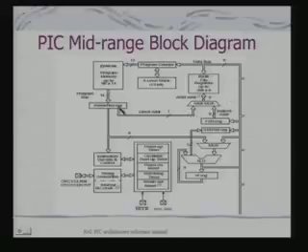This instruction register typically will have the instruction, and it will refer to the registers for operation. So that's why you find a bus connecting this part of your instruction register to the address multiplexer, through which the register gets selected for any kind of arithmetic operation. Okay. So what we will find is that from this register the data would flow onto the data bus, and then it will go into this multiplexer so that it can be used in the ALU for various operations.